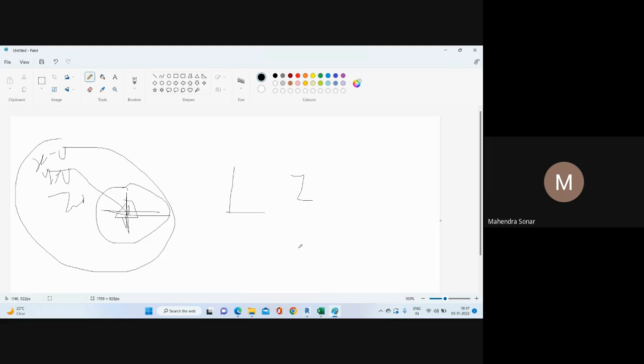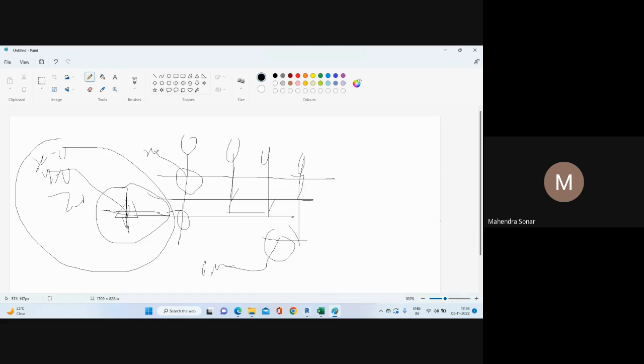Okay, so you need to set this. What we are doing is we need to fix this. This point is our 0, 0, 0. So suppose my geometry or my grid is like that, and I want to fix at any location. You can set here or here. If you set here x equal to 0, y equal to 0, your model is locked at this location. So if the mechanical xrefs your model by shared coordinates, it comes exactly at this location.